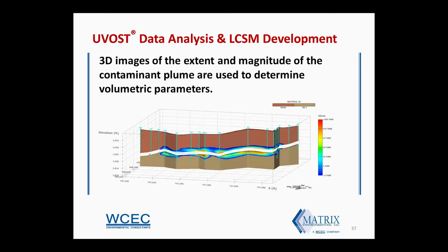What that allowed us to determine was that the NAPL migration at this site was actually dictated by the slope of that interface, and you can see that it slopes in this view from the right side of your screen to the left side of your screen. So this kind of data at this kind of resolution was something that was previously unattainable without a tool like the UVOST.